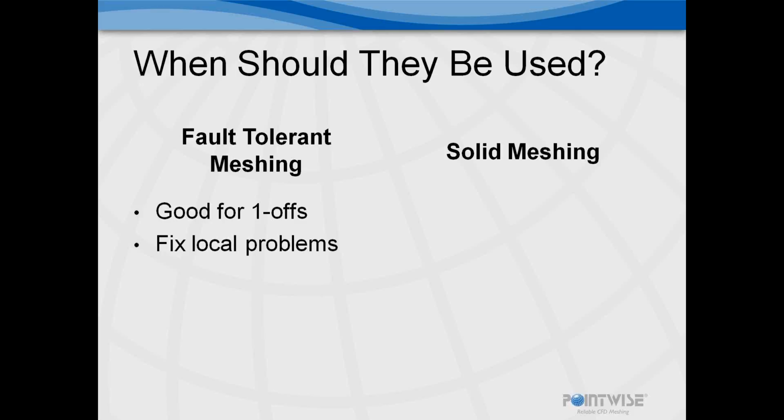but you don't want that to stop you from meshing. And then the last concept, something I use very frequently, is the ability to mesh where there's no CAD at all. I use this approach for far field boundaries and external flow problems where I just need a simple box shape.